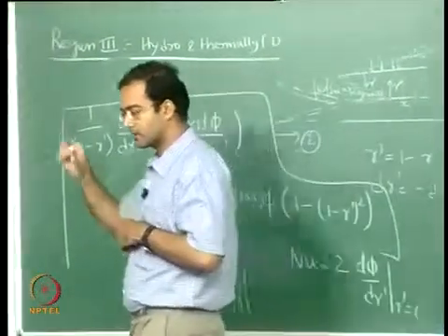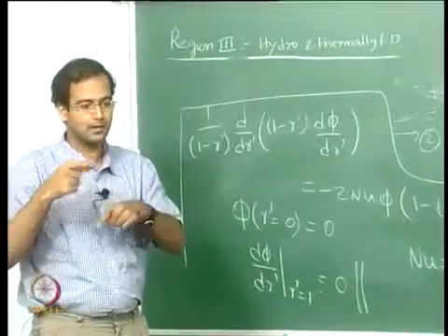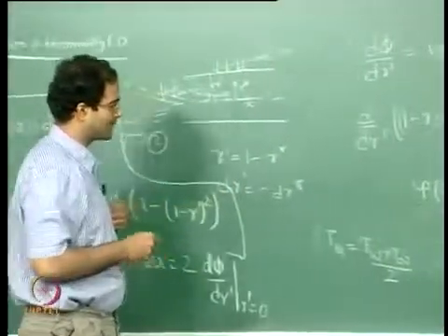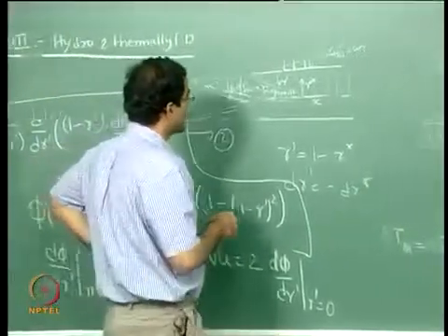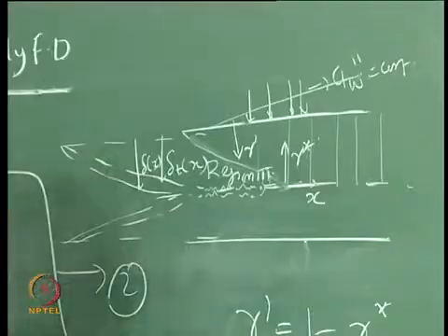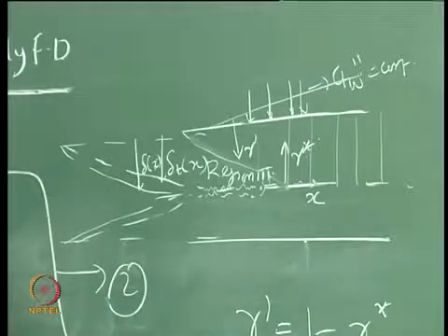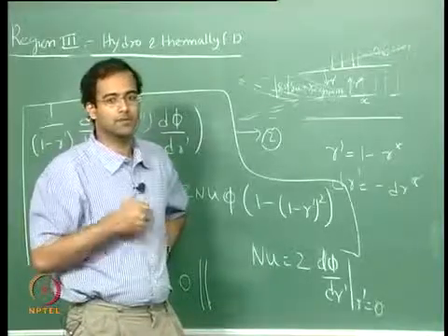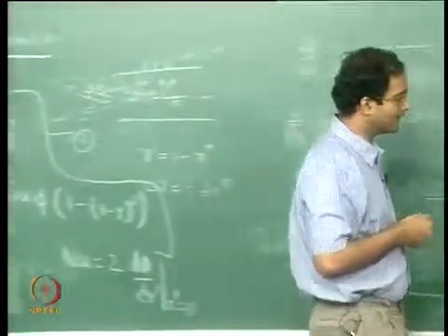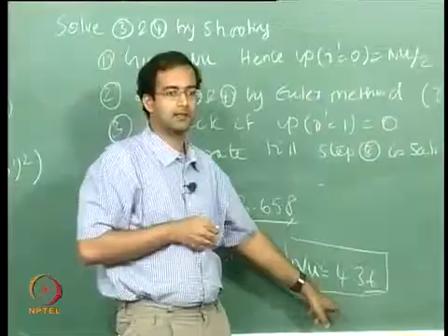Okay, because these boundary layer thicknesses are functions of Prandtl number, and locally the Prandtl number keeps changing due to different temperature values axially. So they attribute that these kinds of disturbances in the thermal boundary layer will possibly result in a higher heat diffusion in the case of constant heat flux, resulting in a higher Nusselt number.